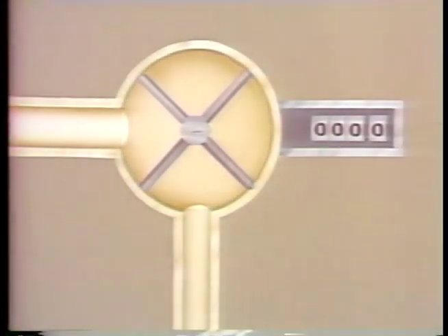One of the simplest instruments used to measure volumetric flow is a positive displacement flow meter. Now, there are many ways to design one of these meters, but this is a typical example. The meter is actually a counter that is connected to a rotating device that resembles a paddle wheel. Each section of the paddle wheel holds a known volume of fluid.